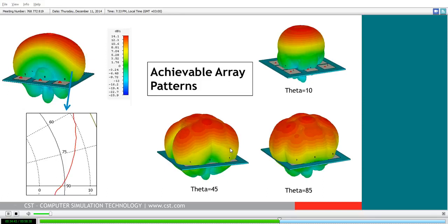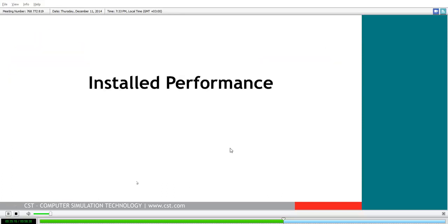If we look at a single azimuthal angle to get a so-called cut of this performance, we can see that really we're only hitting our 12 dB target out to about 60 degrees in this case before we're degrading below that gain. Although even right at 90 degrees, where this substrate is practically end firing off of the edges, or perhaps there's some diffraction effects there from the edges, we're actually not too bad off. We're still getting around 4 dB gain there, right to the edges of this design, which is pretty promising.